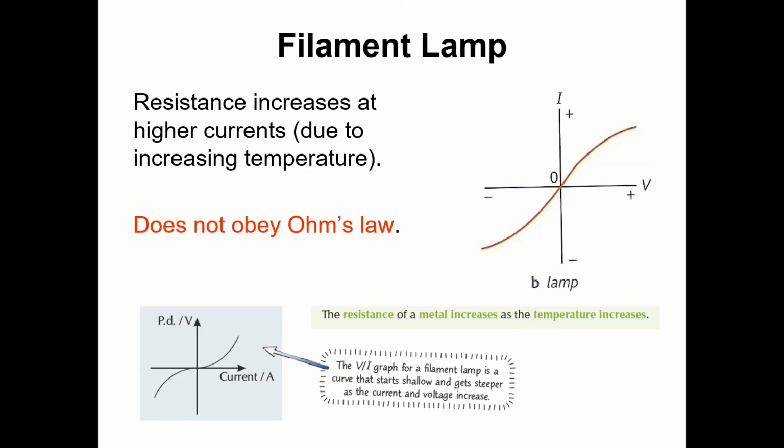If you have to find out resistance at a given voltage and current, remember never to say drawing a tangent or anything like that, okay? Because often with other curves, you might draw tangents, but certainly not with this one, okay? So you're finding a resistance at a given voltage and current, so you just take a pair of coordinates.